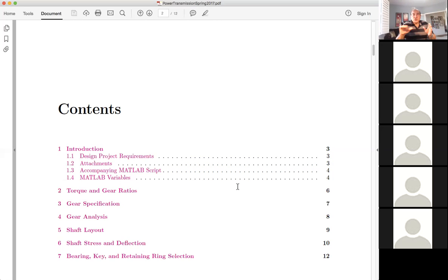We have to have a shoulder, so we have from small to large size. And then we would also have to have grooves to attach retaining rings or set screws or other features that will ensure that the gears can be assembled and disassembled easily.